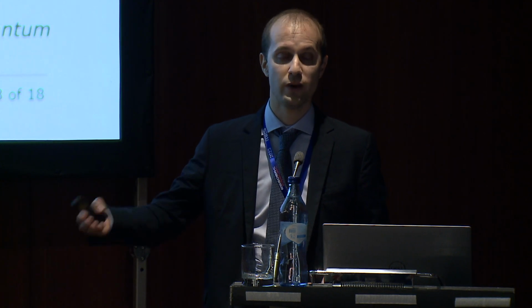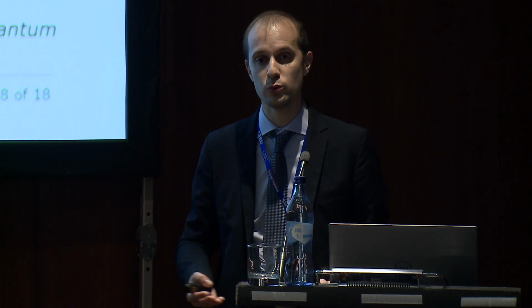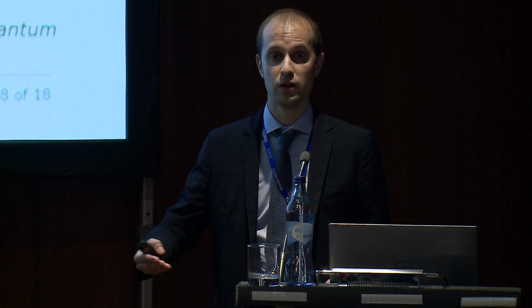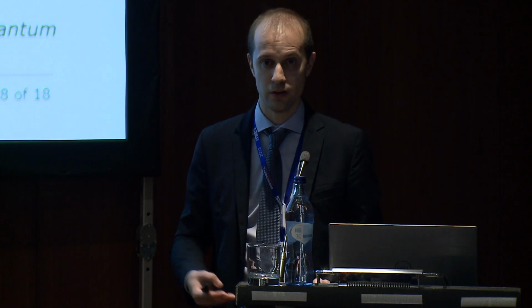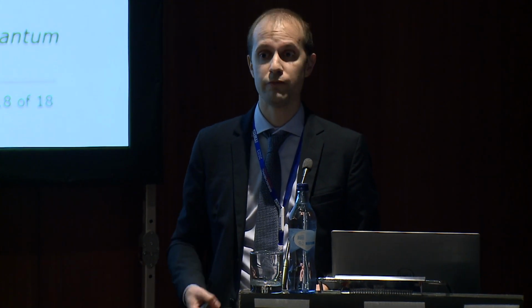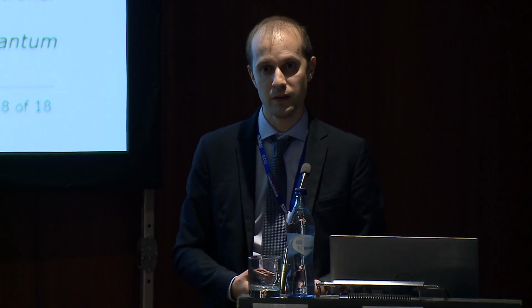And then in the future, it should be even less because 1 milliwatt per qubit means if you have 1,000 qubits, you consume 1 watt, so you're already at the edge. So you should be able to scale this down. And this should ideally include the transmitter for control, the receiver for readout, and also the clocking if in your system you plan to integrate that as well.